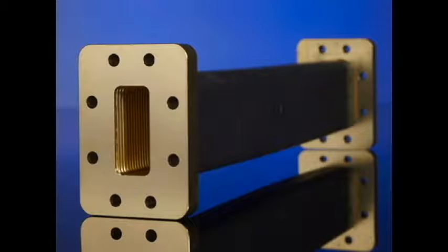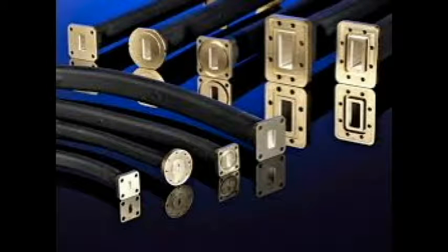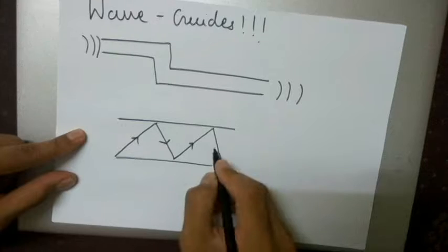Without the physical constraint of a waveguide, waves decrease according to the inverse square law as they expand into three-dimensional space. There are different types of waveguides for each type of wave. The original and most common meaning is a hollow conductive metal pipe used to carry high-frequency radio waves, particularly microwaves. The geometry of a waveguide reflects its function. Slab waveguides confine energy in one dimension, fiber or channel waveguides in two dimensions. Due to the total reflection at the walls, waves are confined in the interior of the waveguide.